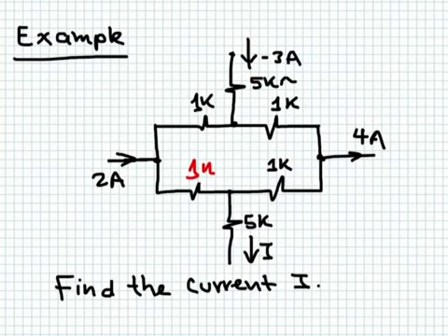Now I would like to determine I using this given information, using KCL. This is my target in this question. So there are 2 approaches. The first one is a brute force application of KCL. I don't know what the current flow is here, so I'm going to define a current here, and another current here, and I will assume they flow in this direction.